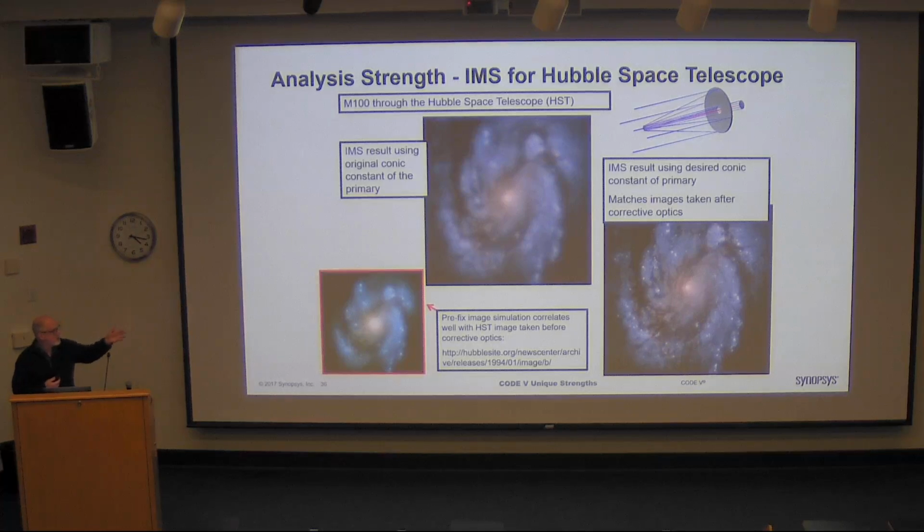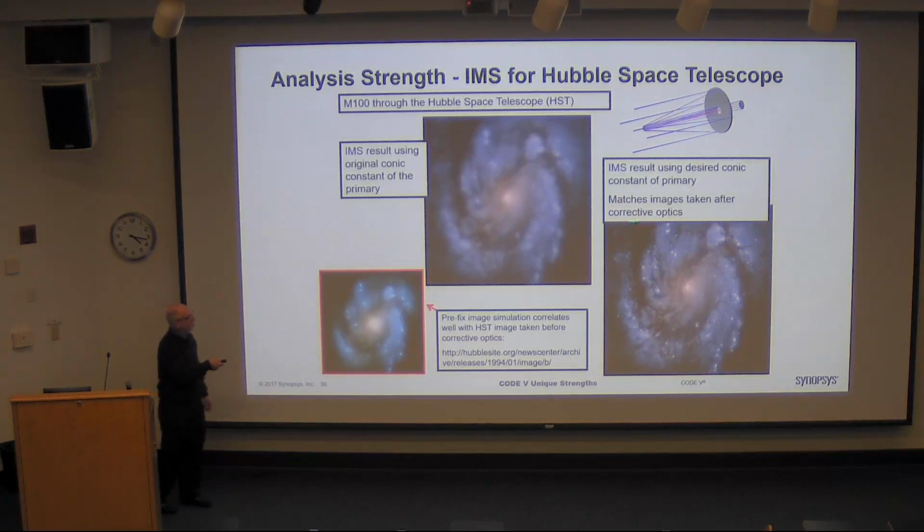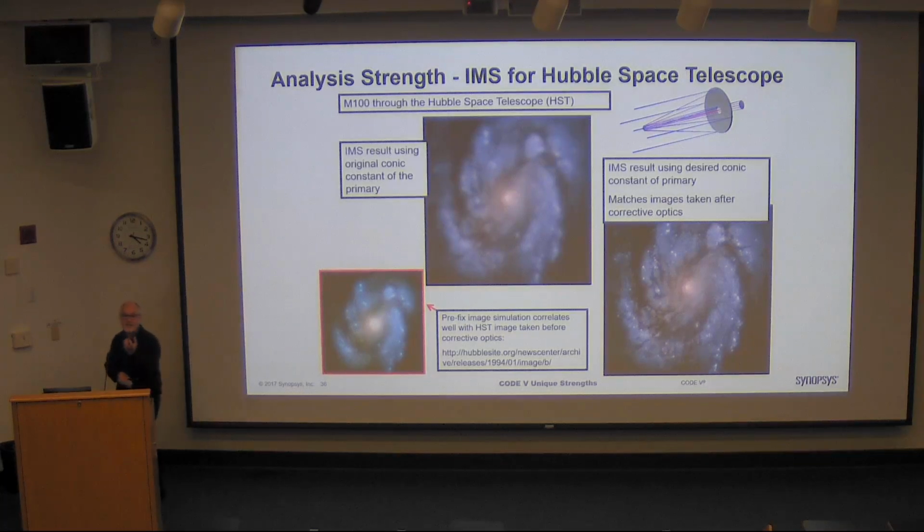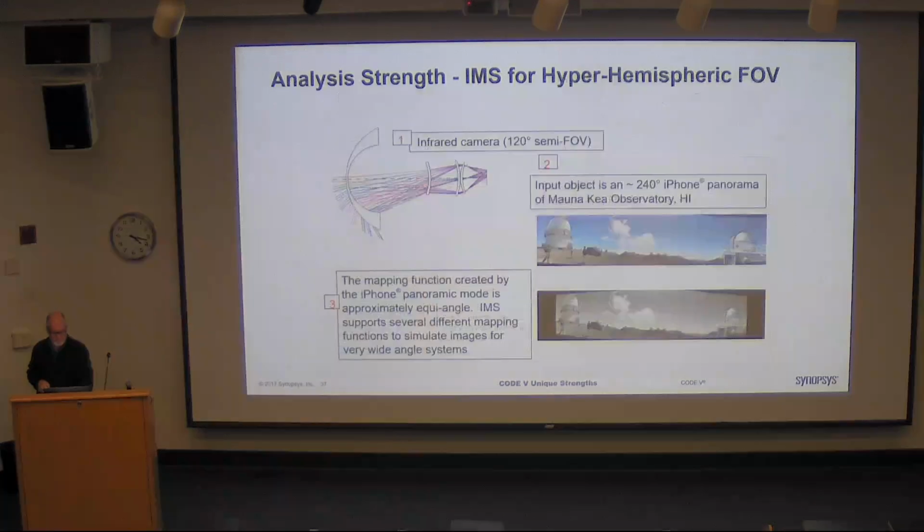But what this feature is doing essentially is it creates a point spread function map across the format of the object, and then does a convolution of every pixel with the point spread function. Even if we have a very high density image, we can do a linear interpolation between the point spread functions we have, to synthesize point spread functions based on the values in the grid. This gives faster performance, a little less accurate, but faster calculation time.